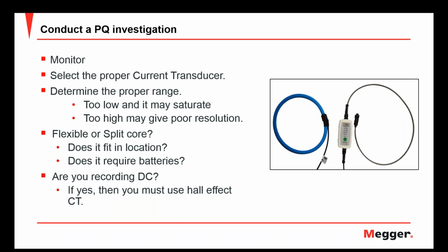Now, on the other side, if you go too small, you could end up saturating. That's why it's important to understand what that crest factor is for the current clamps and the current channels in the unit.